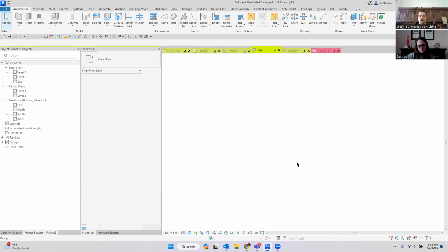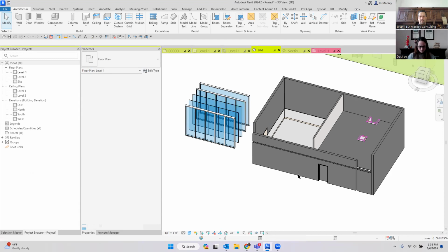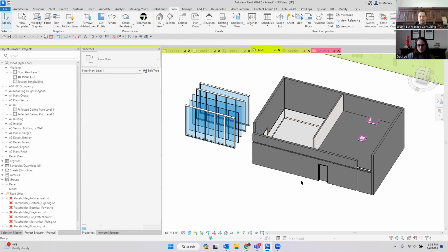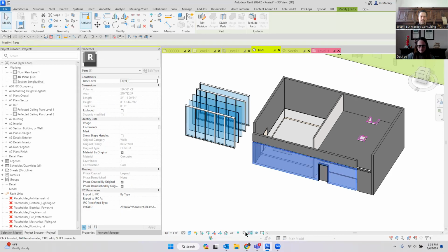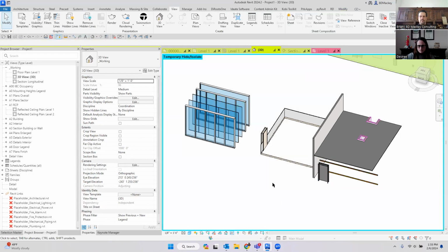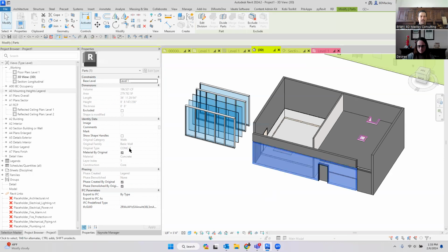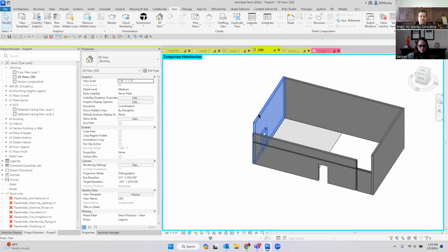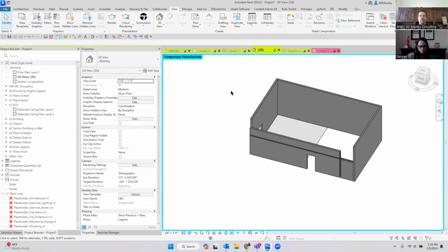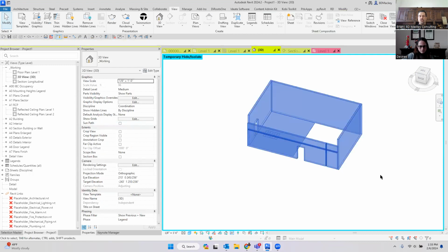So let's just see. We're gonna come in here and grab parts. Love Zoom in Revit. I'm gonna go isolate the category with my sunglasses. I guess I didn't get the parts category there. That is a part. I have a part. Sunglasses. Isolate category. It was funny, it even gave, oh, because I did part out all the walls. Right, I just did a giant selection window.